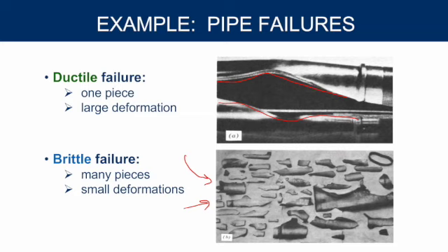Whereas with this one, you get warning, you see a deformation, and even if it does split, you have a much lower chance that it splits in a certain direction. It might be straight up, where it wouldn't affect the person walking by. I mean, there is a chance that it would go in the direction that people are walking, but there's a much lower risk of fatality from this system, and there's the predictability. You see a lot of deformation before it fails, which gives you the opportunity to fix it.